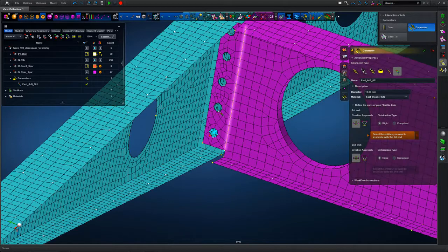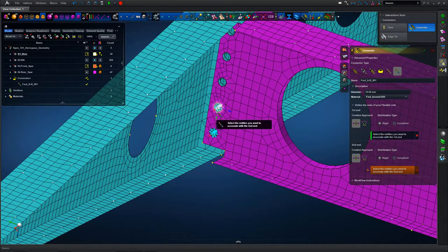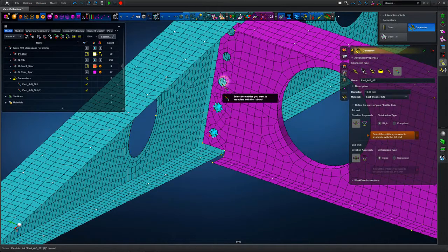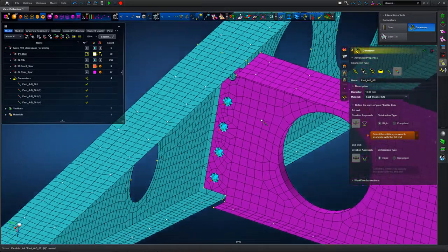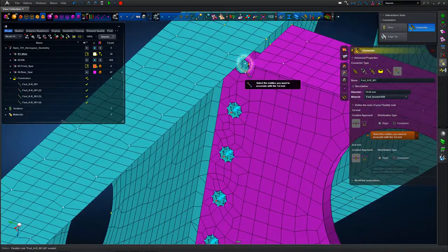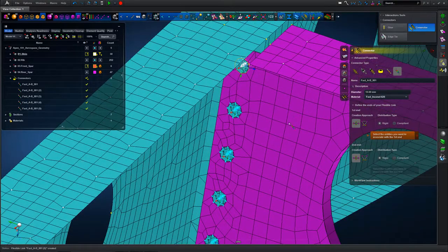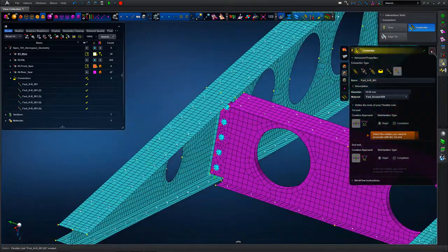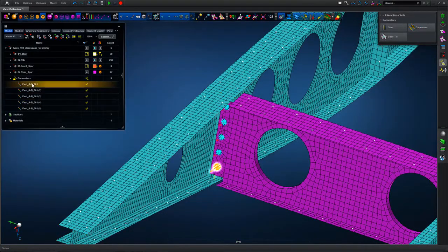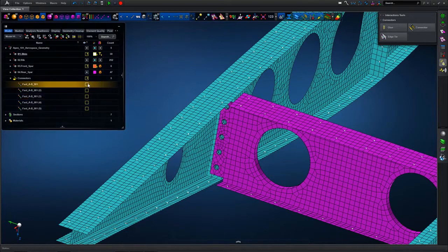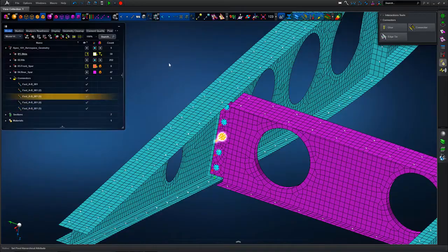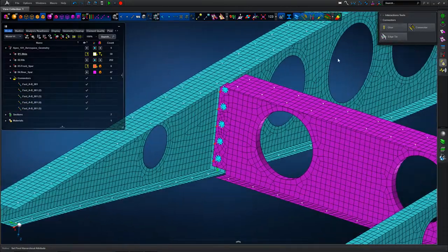So we can repeat that for all of the interface fasteners in this region. So again, Apex calculates the center of the hole and generates the fastener between the two center points for those holes in the connector definition. So again, very straightforward and visible within the model browser tree, both in terms of viewing and or editing. So for clarity in terms of what Apex is doing.